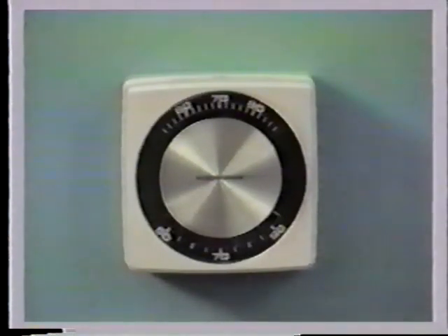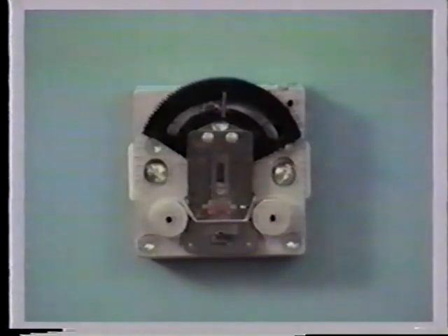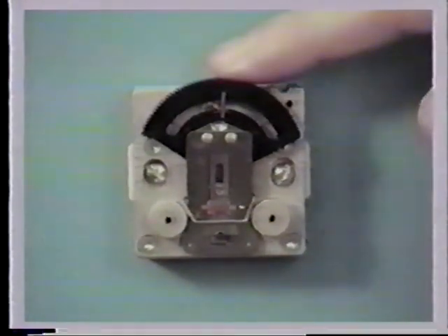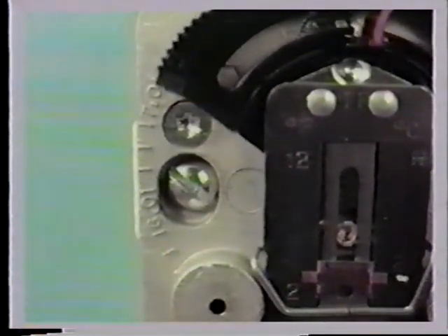Shown here is a two-pipe room thermostat, the 2212-118. One of its more prominent features is the set point adjustment and indicator. Note also a temperature scale on the face of the thermostat body, which can be read off the end of the set point adjustment. Settings can be made or changed without the cover being installed on the thermostat. This aids in calibrating the thermostat.